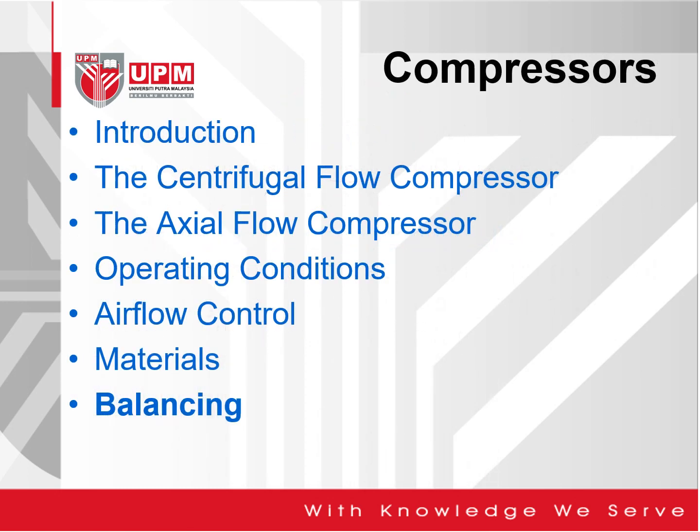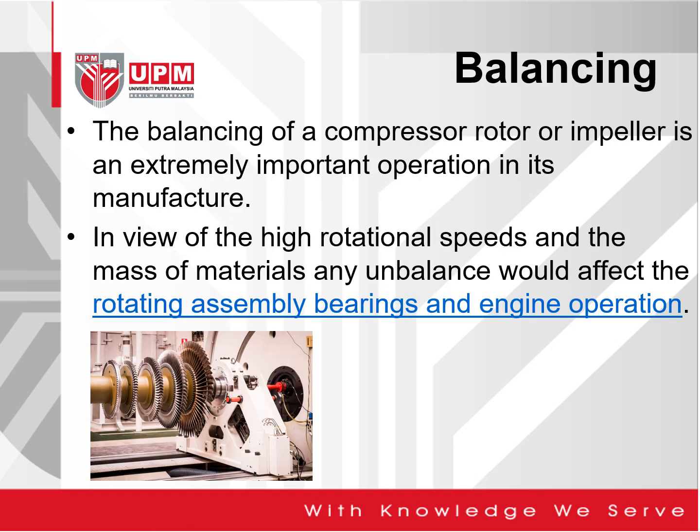Finally, it is about balancing, and we want to look at what balancing looks like for a compressor. So at this stage, balancing of a compressor rotor or impeller is an extremely important operation in its manufacture. In view of the high rotational speeds and the mass of materials, any unbalance would affect the rotating assembly bearings and engine operation.